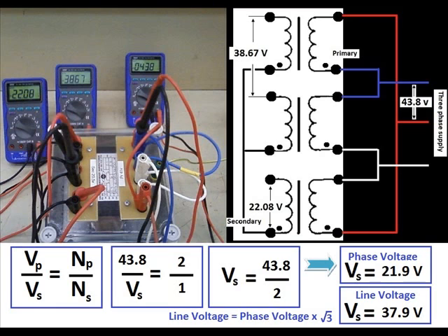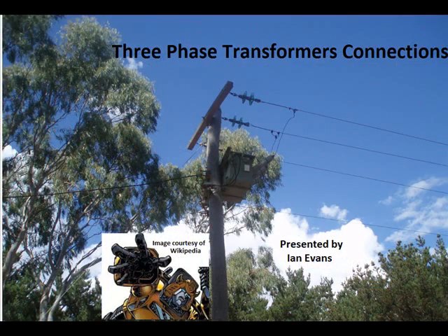So you can see from that the four different ways to connect the transformer, and the varying voltages that are available from those different connections. The final testing of transformers before energizing, of course, must be done in accordance with the verification section of the AS/NZS 3000:2007, and also for portable transformers, in accordance with AS/NZS 3760.